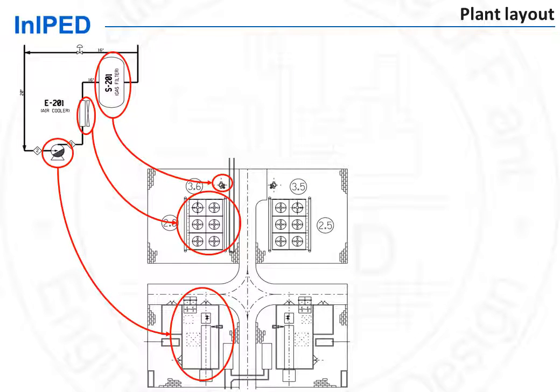In the case shown here, for instance, that includes a gas compressor and an air-cooled heat exchanger, inquiries will have to be made to vendors of these two equipment, the gas compressor and the air-cooled heat exchangers, to get dimensions in order for plant layout to be able to produce the unit plot plan.